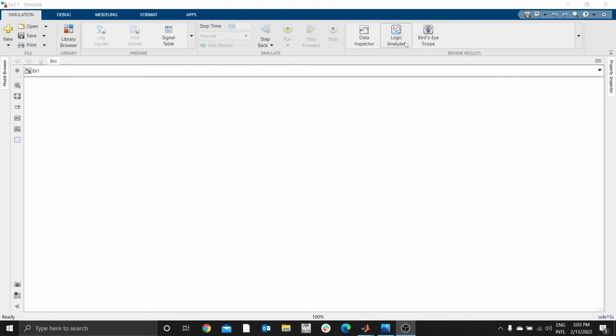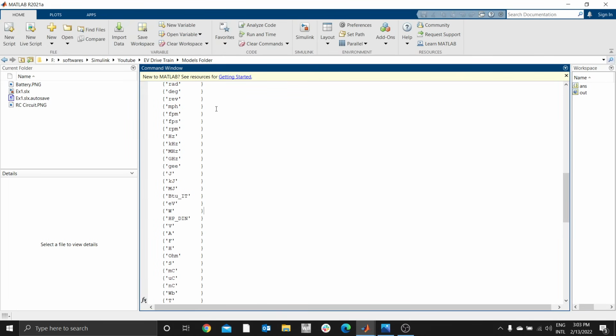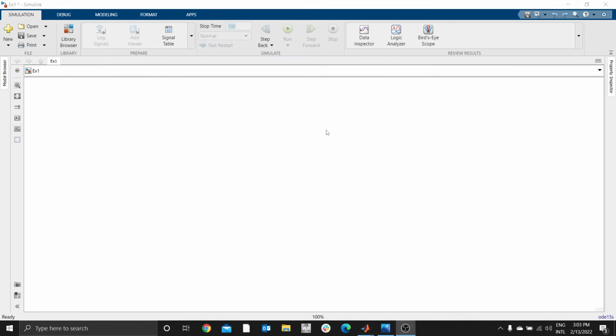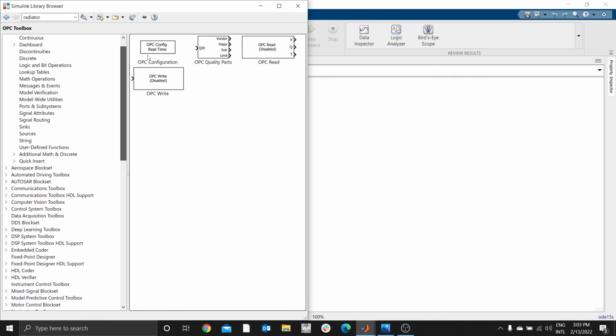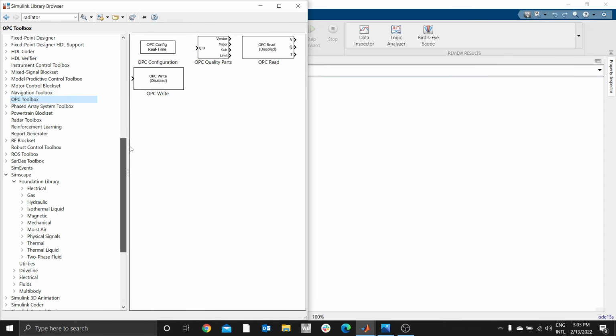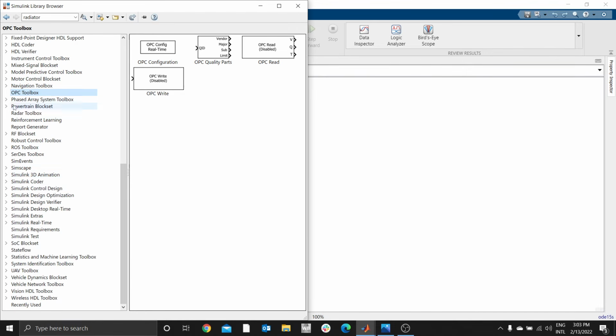Let's now start. You need now to open Simulink from your MATLAB. If you go to MATLAB here, the Simulink, you just click it once, it will open. Okay. Then in the Simulink environment, we have various libraries to be used. As you can see, there are very many depending on application. Today our main focus will be Simscape. We're going to use Simscape here.